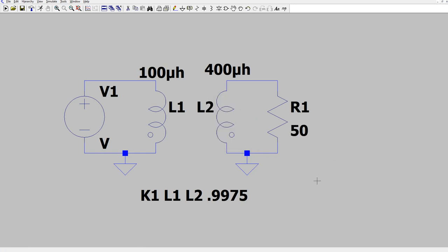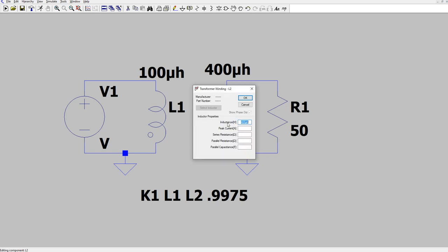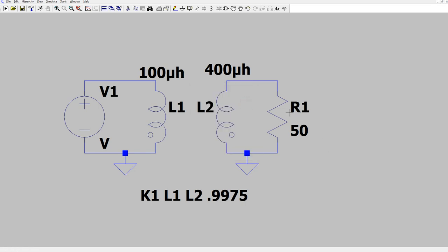To set a component value, you move the cursor over the component until you see the little hand, and you right-click on it, and you can put in the value. If you're not in the right place, like if you're here and you click it, you'll be editing the text instead, or some other parameter, like the reference designator here. Okay, so you have to be over the component.